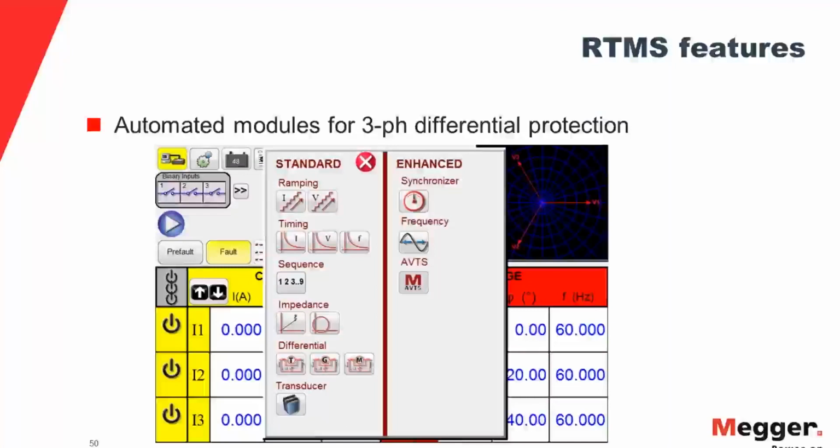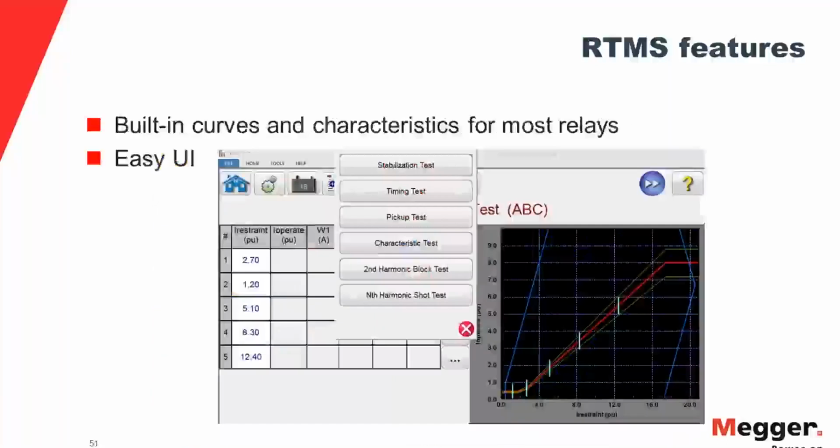Having said that, the SMRT46D offered by Megger provides 4 voltages and 6 currents. It has convertible voltage channels that you can convert into current channels, so you can test either the single-phase or the 3-phase differential protection scheme at the same time. If you are doing bus differential and more complex procedures like that, then the SMRT410 might be an ideal option because it has 4 voltages and 10 current channels, which will be sufficient to test one phase at a time on the bus differential as well.